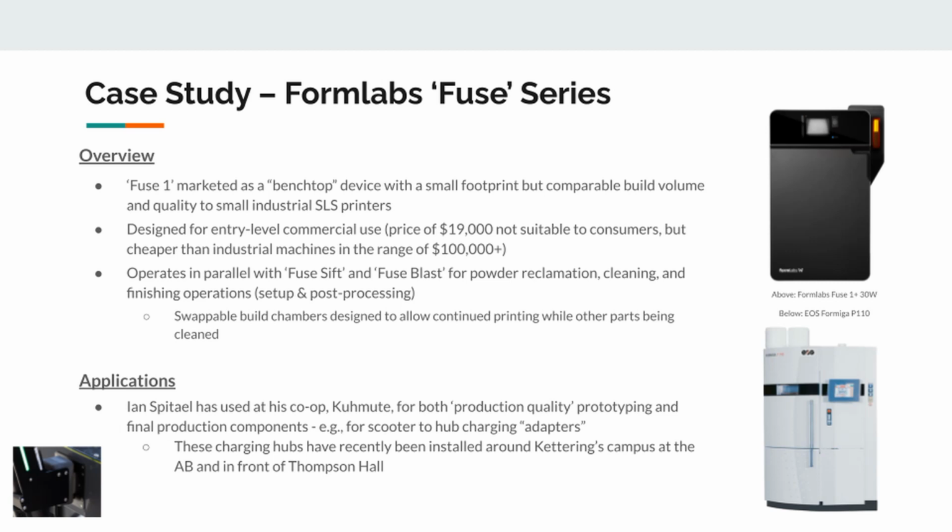In my experience, the SLS printing process itself is relatively simple to execute, as the software and printer handle most of the settings and part packing automatically. However, the setup and especially the post-processing steps can be quite labor-intensive. Without having an automated solution like the Blast, I've spent numerous hours manually brushing powder away from batches of parts and then sandblasting them. While experience has made me more efficient over time, I still can't achieve completely uniform results, especially in sandblasting, where we risk leaving a surface slightly marred and darkened if the air gun is too close to the part or held in one spot for too long.